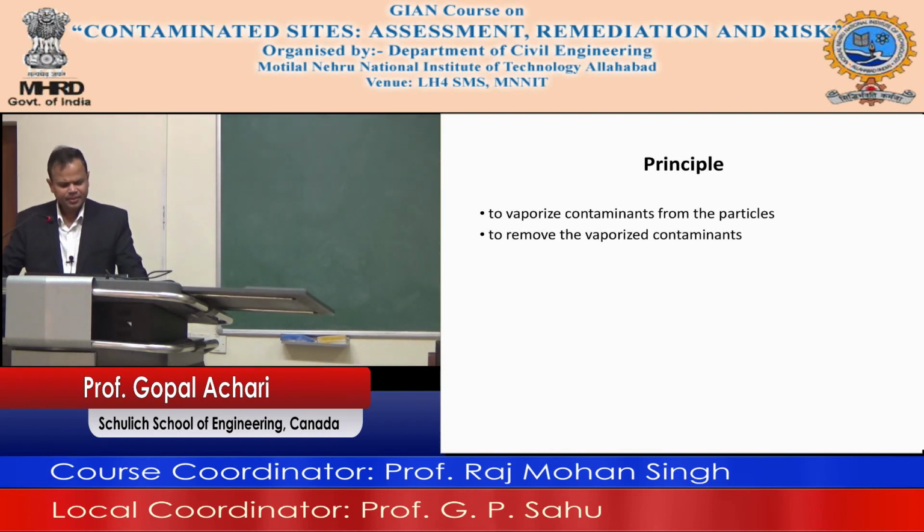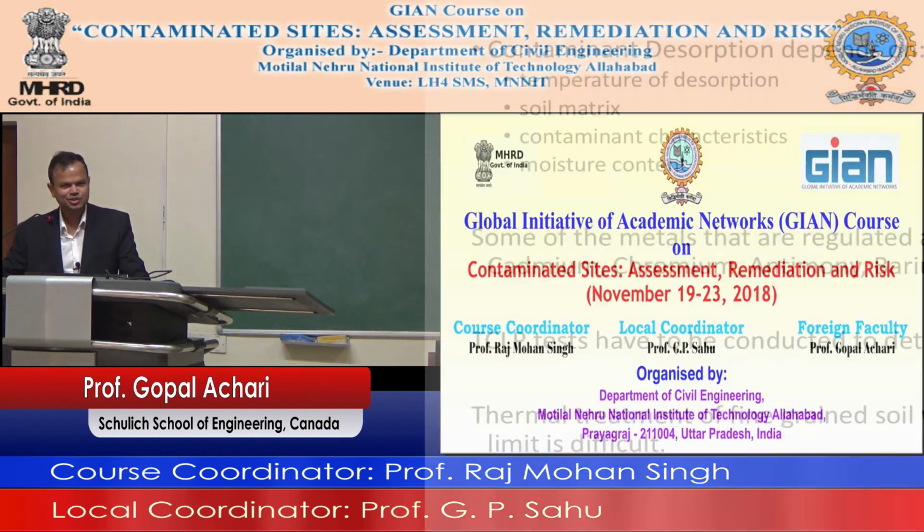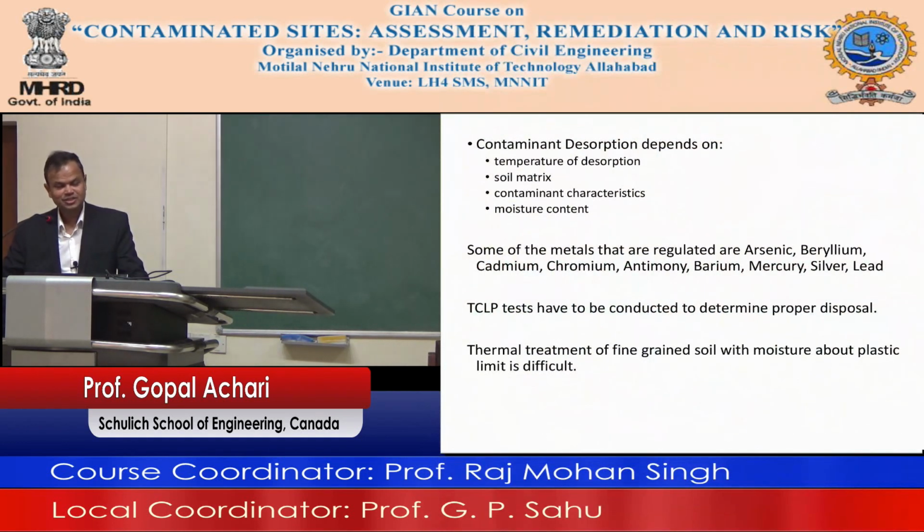So the contaminant desorption depends on, now let's look at the desorption phenomena. What does it depend on? It depends on the temperature of desorption. Okay, what temperature are you desorbing? Of course, the heavier the hydrocarbon, the higher the temperature you might need. The matrix itself, okay, if you have sandy soils with hydrocarbons in it, it's a lot easier to desorb sandy soil, let's say dry, as compared to, let's say, clay soil with lots of moisture in it.